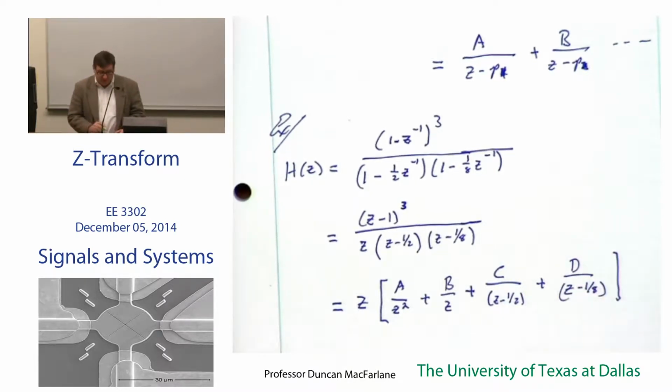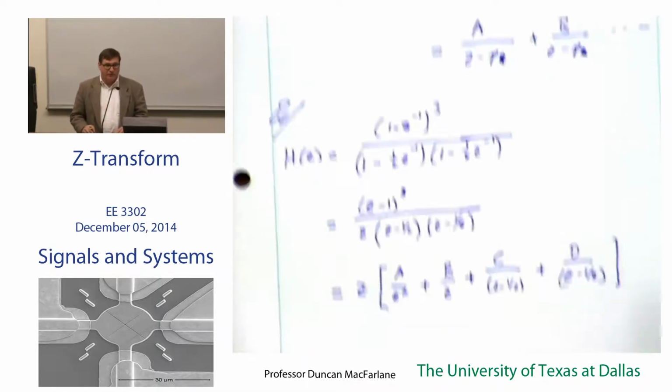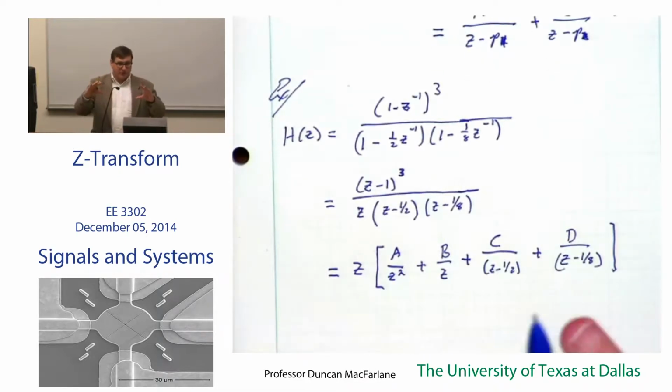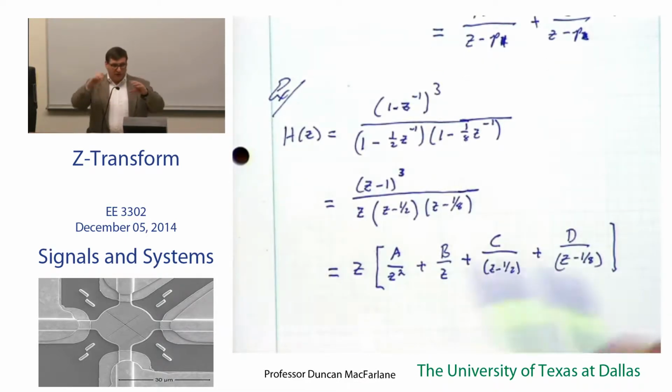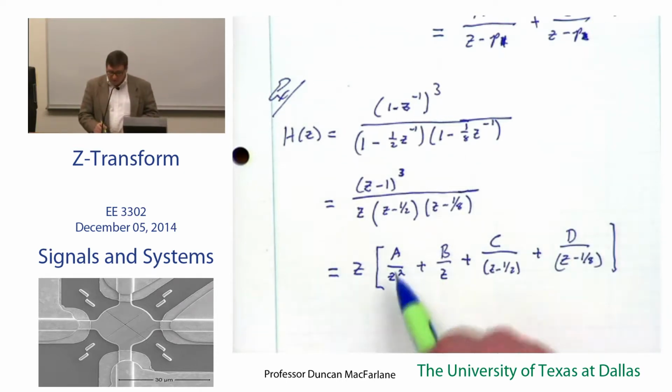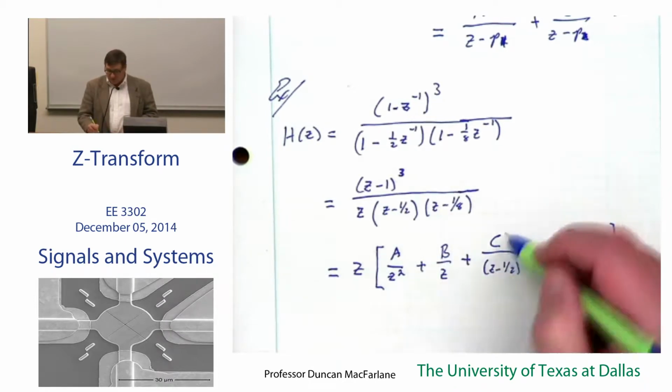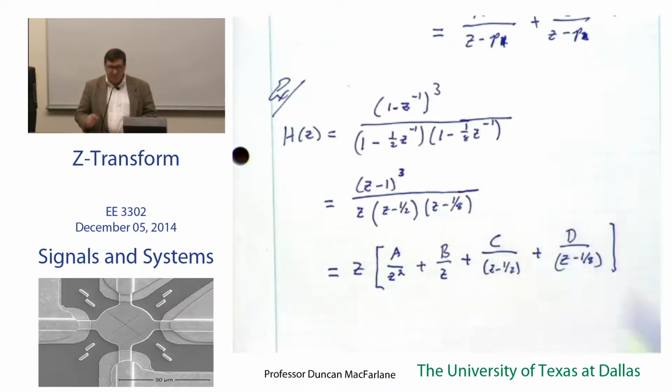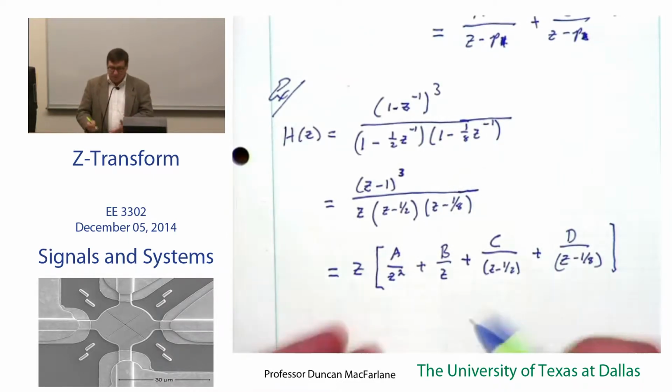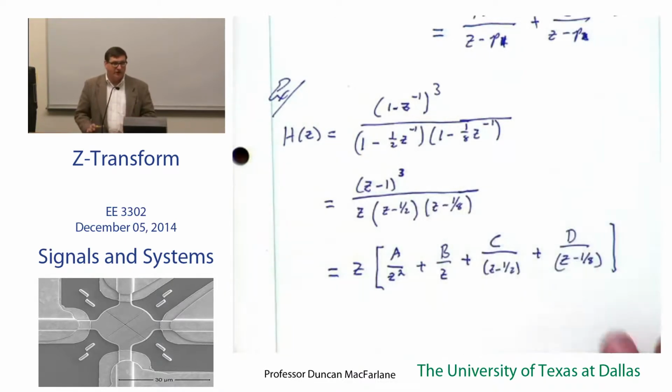And so now you can see that if instead of building this as a feedback loop with the direct form 1, instead of realizing this as a cascade, I realize this as a parallel connection of a 1 over z squared, a 1 over z, a feedback loop here, and a feedback loop here. So 4 structures in parallel will do exactly the same as the other 2.